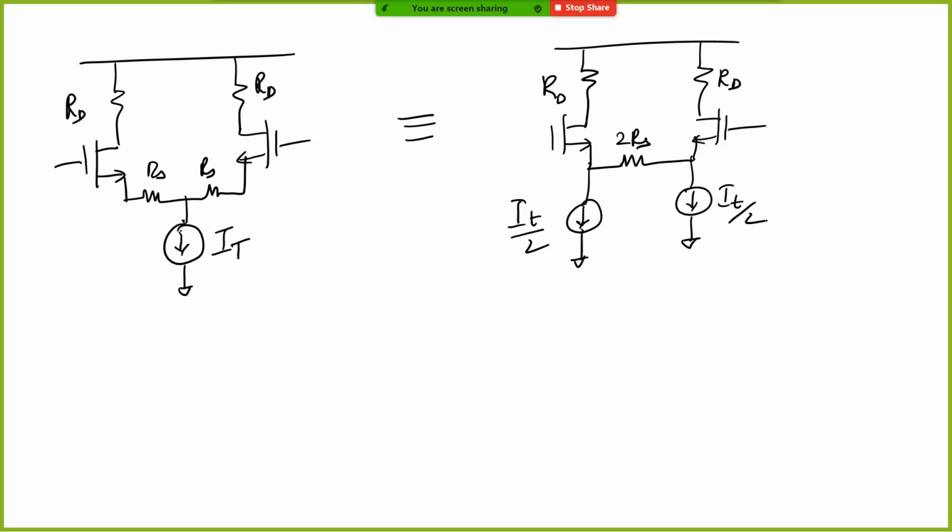Now, how do you analyze a circuit like this? Instead of a resistor, you can have a capacitor, you can have any kind of thing. How do you do this? You just draw the half circuit. Basically, it becomes like this. You have Rs, and of course the virtual ground is in the middle. This is a DC source, so this will be your differential mode half circuit.